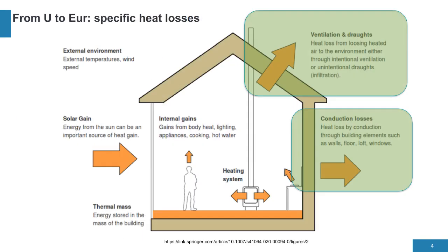So, how can we evaluate these final indicators related to our buildings? We will analyze building energy consumption starting from the U value and incorporating other necessary data. First, we will calculate the specific heat loss, H, which describes the actual building considering its architectural solution. Generally, heat losses must be compensated by internal gains, solar gains, and the heating system. Internal and solar gains are free, but the operation of the heating system is what we pay for and what